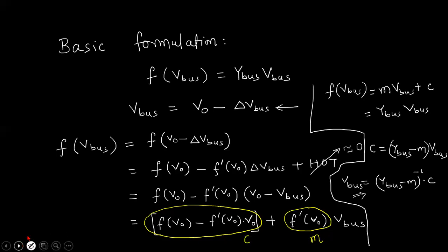Okay, so let us take the example of a general distribution system. Here we have bus number one as a substation, and the system can be radial in nature, or there can be some branches emerging out of some buses, or there can be loop formations. Does not matter. So here we can write the bus injections, which are basically the currents injected at respective buses. So I1 represents the substation bus injection, followed by I2, I3, and so on up to, let us say there are n number of buses.